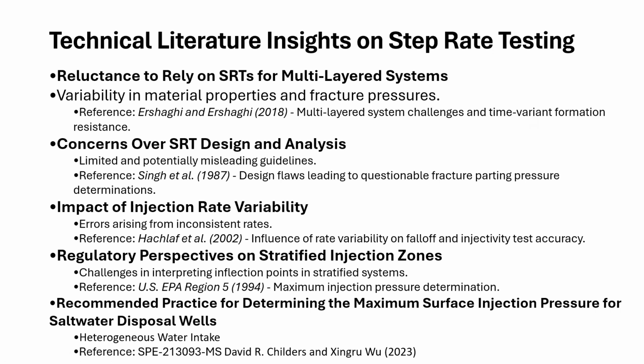So this all being said, there are a lot of technical insights on step rate testing, and you'll see a reluctance from many authors to rely on step rate tests in multi-layered systems.